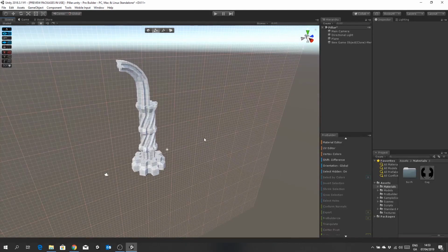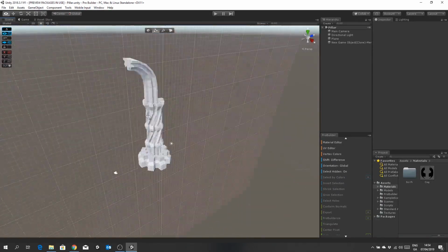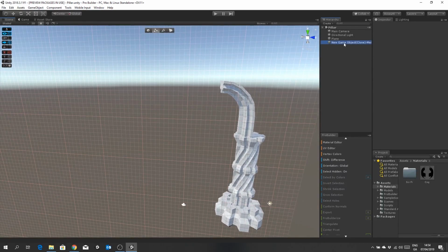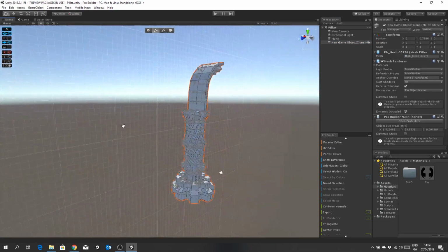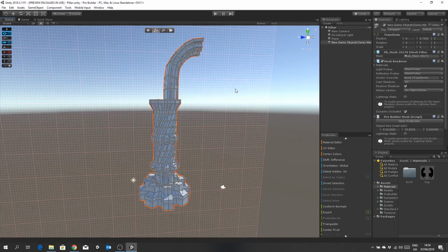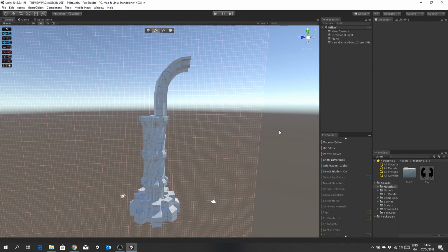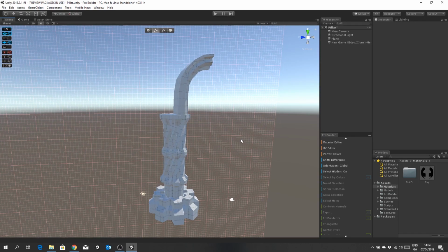Yeah, so as you can see, you can do something pretty cool, pretty fast. And all of this geometry can be exported out into the standard formats, like I think it's OBJ. There's another couple of types as well. So if you wanted to do some extra work in an external package, bring it in and fix up whatever faces or whatever. You could trim out certain parts of the geometry if you wanted to, if you're more comfortable in another package. But what's nice about this is it's already there. It's sitting inside Unity. It's collidable. Its UVs are okay. They're not perfect, but that's something you can also fix inside here. We'll leave that for another lesson.